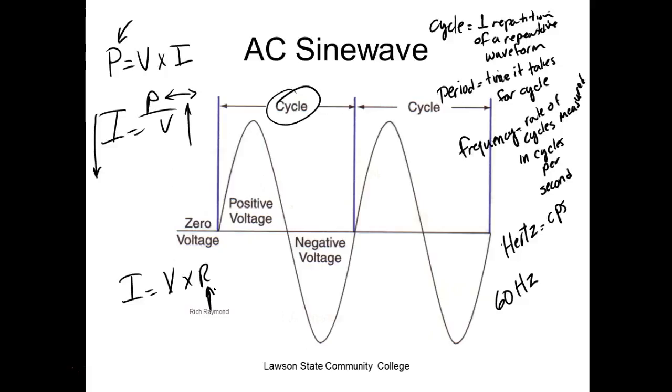So these high tension lines, they're way up in the air because they're using air as an insulator. And the insulation of air varies, right? It's a good insulator, but it varies with moisture. Alabama Power is referenced to earth ground, so that wire, that power is trying to get to ground, so we have to insulate it. We insulate it with air, but they get it up way high, right? And of course, the closer they get to me, they have to start getting it what? Closer and closer to ground. What do they start doing? They drop the voltage down with what? With transformers.